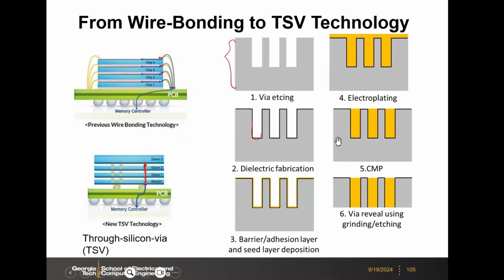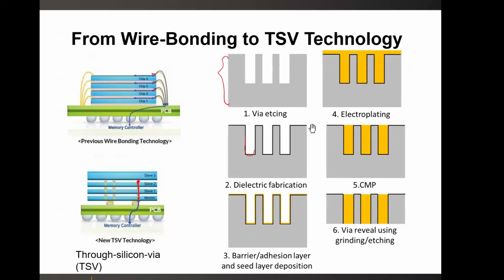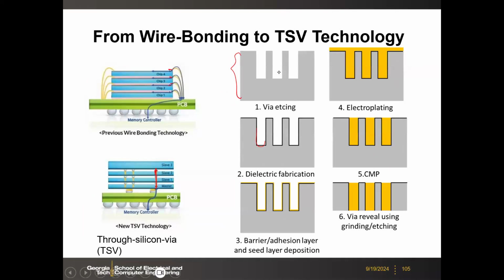So basically you get rid of the additional silicon. Then you make this copper wire through the silicon. Typically, the silicon wafer as fabricated is a few hundred micrometers thick, and after this thinning process, you reduce the wafer maybe to tens of micrometers or even a few micrometers thick.